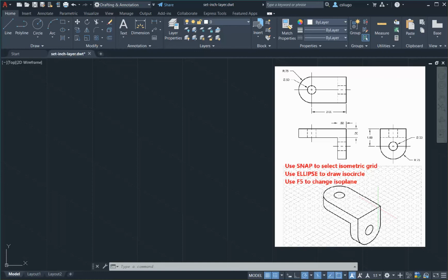And the rectangle I'm going to draw, let's start with the top one here. Just by looking at the model view, I know this rectangle, the top box, is like this box over here. It has a height of 0.5. It has the width, which is this part here. It's going to be 0.75 times 2, which is 1.5.